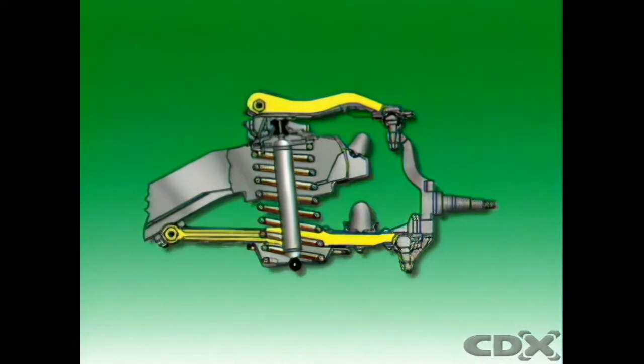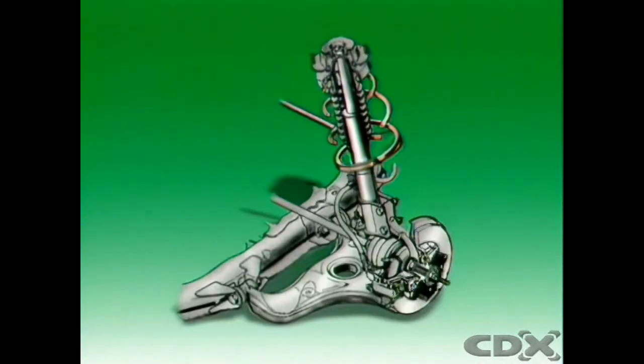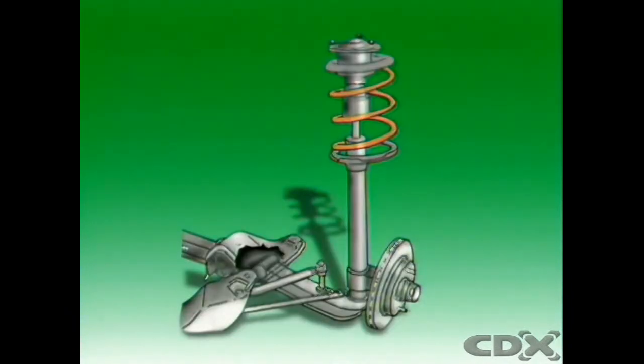Parallel link front suspensions have two control arms. Vehicles with strut-type front suspension have only one arm. It can be a wishbone shape with two fulcrum mounting points or straight with single fulcrum. The inner end of the control arm is bushed to the vehicle body, and the outer end uses a ball joint to allow changes in the steering angle for turning.